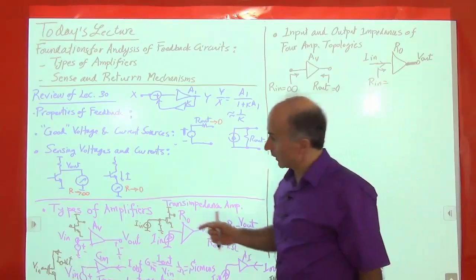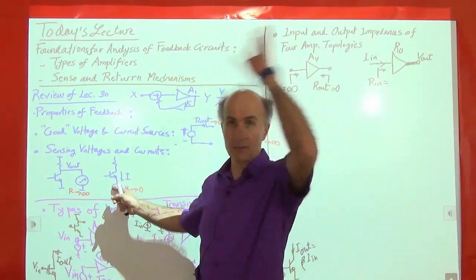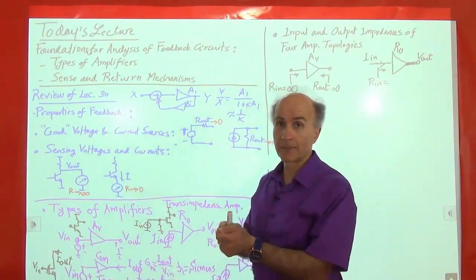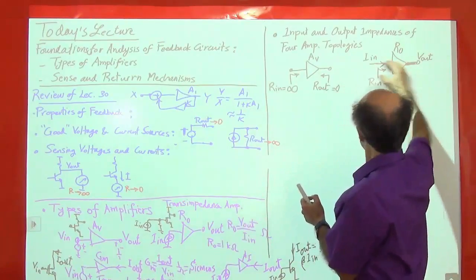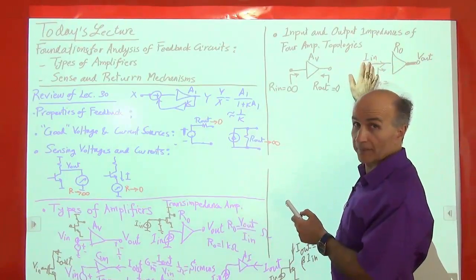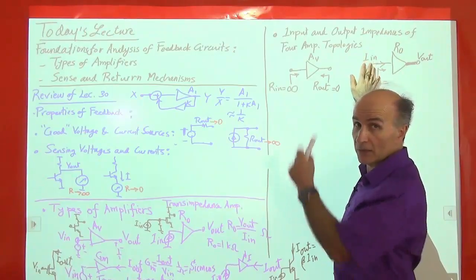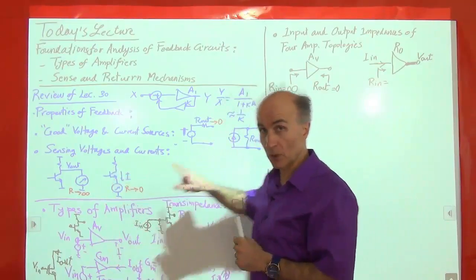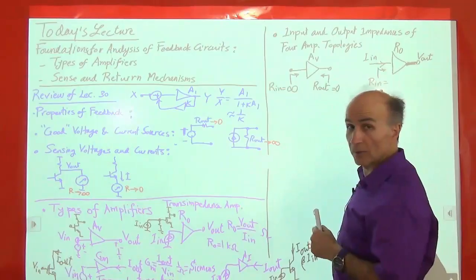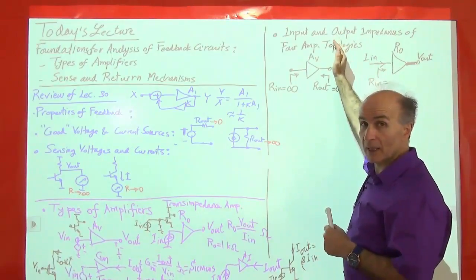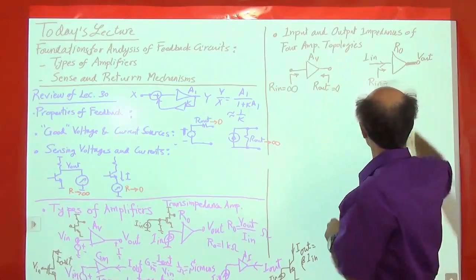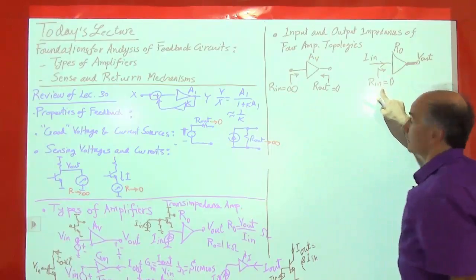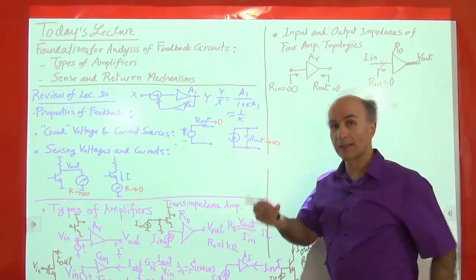All right, so remember, we're trying to measure a current somewhere in some system. And when we want to measure the current, there's a current through some wire somewhere, right? And we want to cut that wire and put this guy in there to measure that current. That's this job. So this guy must not disturb that circuit, just the way this current meter must not disturb the circuit. So the input resistance of the circuit must be zero, so that when we connect it to that preceding stage, that stage doesn't feel it. So this should be zero. I know this is very unintuitive, right? This is difficult to understand. But as we go along and we look at examples, you will see.